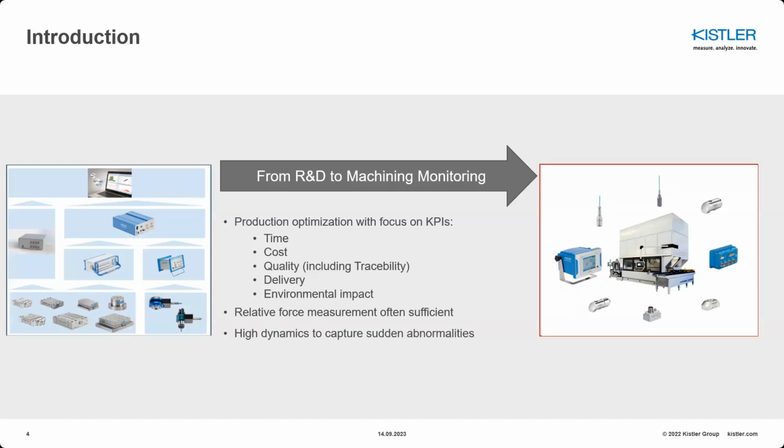We are working with machining, so we have high dynamics, we have rotary tools, we have rotary workpieces. So you need certain technologies in order to capture those high dynamics, like piezo technology. Of course, there is automated evaluation and more AI coming into the picture, but still the evaluation part has to have certain intelligence, right? Not like what we are doing in R&D, where we gather a lot of information and try to analyze it. Here in production, it has to be automated. And also, of course, the system should not interfere with manufacturing execution, both hardware and software.